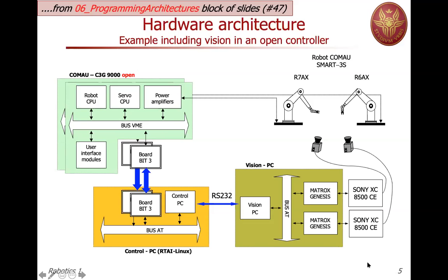So this is not only including vision and your own external controller, which could be done also on our KUKA robot, but it is the presence of this board that connects directly, and of course a real-time operating system, real-time Linux running on the PC, that could enter into the core of the controller. So substitute what the original controller was doing at the level of current or torques. Okay, but this is not the case in our setting.